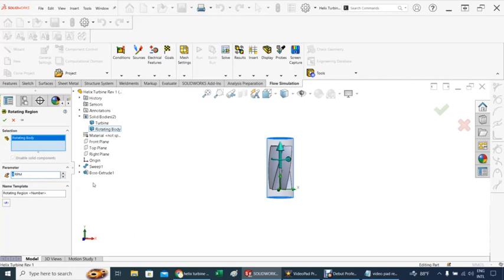It's not a problem of SolidWorks, it's a problem of how you want to handle this, because you have to specify an RPM. For example, if I specify 0 RPM, it means that these blades are not moving at all. So I would say that's the maximum torque that this blade will have. Maximum torque meaning no horsepower.